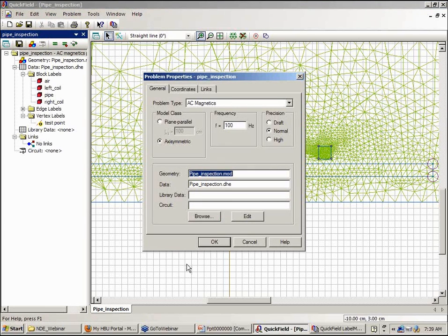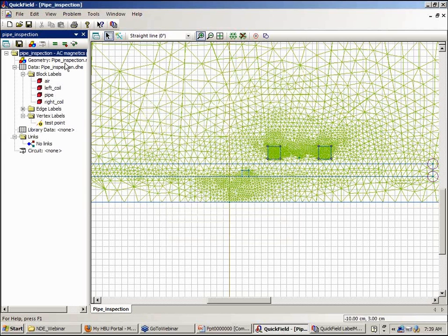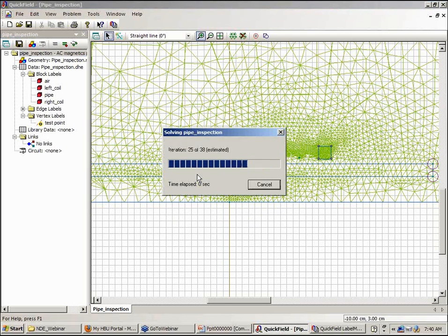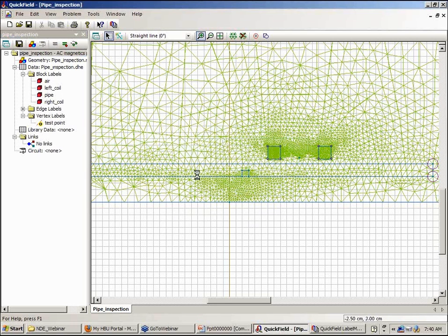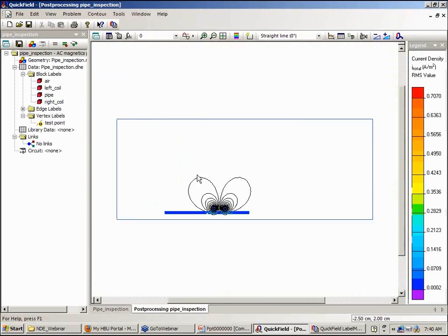This is essentially 100 hertz, which wouldn't be in the operating range of a pickup coil. However, a Hall effect sensor, flux gate, or a SQUID would be more suited for the ultra-low frequency range.